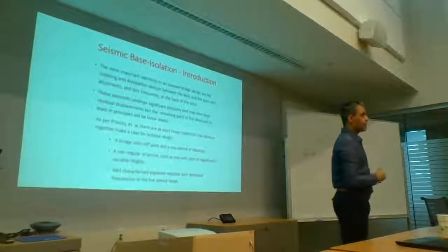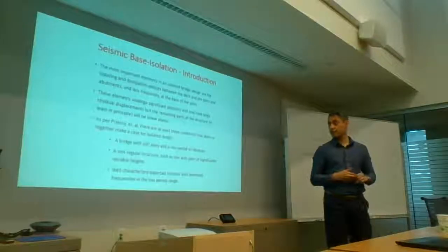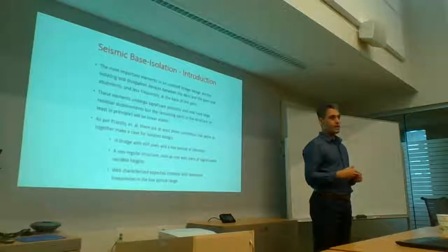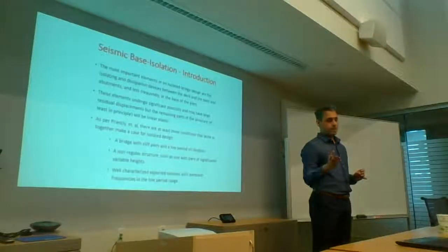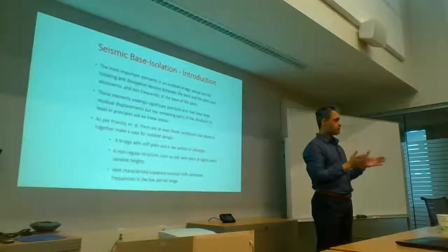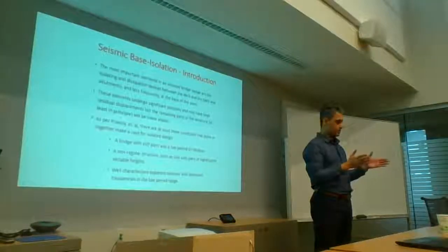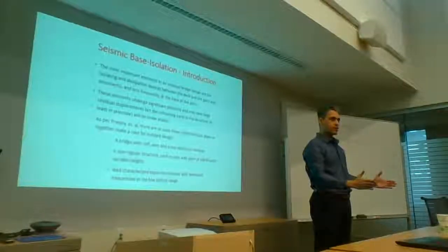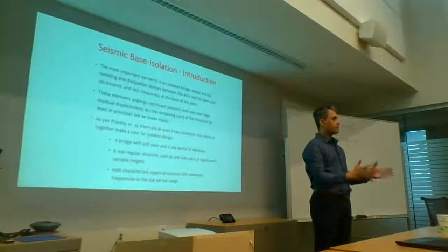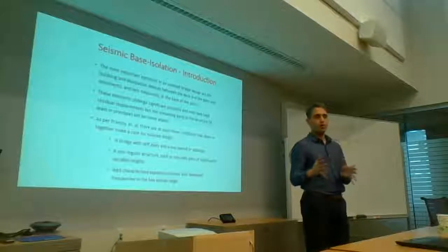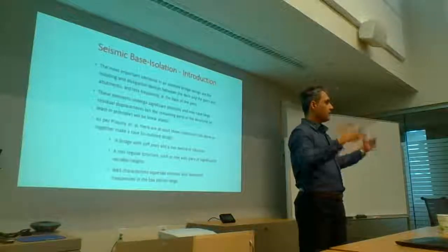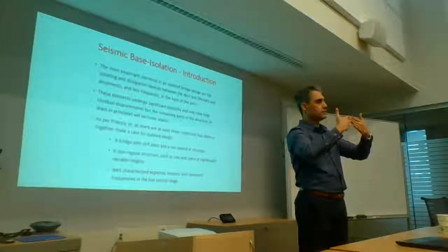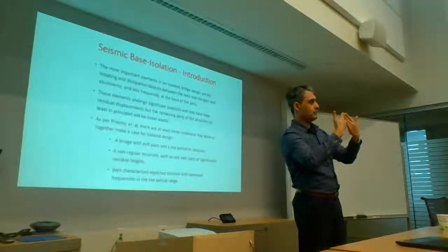I visited Pakistan after the big 2005 Kashmir earthquake, and I was looking at a lot of the schools there, and it became very apparent to me very, very quickly that it was the construction that was primarily responsible. But when you look at the construction up in the north, it's very shoddy. These are unreinforced stone masonry walls that are 2 feet wide, and you've got these light wooden trusses sitting on top as the roof or the ceiling.